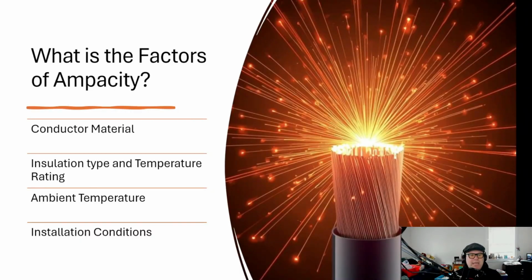And over time, they said, hey, let's say 12 wire, at 20 amps, at continuous use, slowly the insulation will degrade at whatever time frame they find. But what happens is the insulation gets brittle. If you use it over the capacity, it gets brittle and it falls apart. And if it's touching a ground or neutral, that insulation breaks, and now it causes a dead short and possible fire or possible death. Because if someone's sleeping, the fire happens when they're sleeping. It's sometimes hard to hear that arc when you're sleeping too, but the next thing, else is burning down. So that's ampacity.